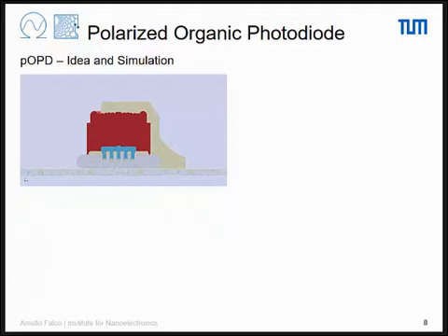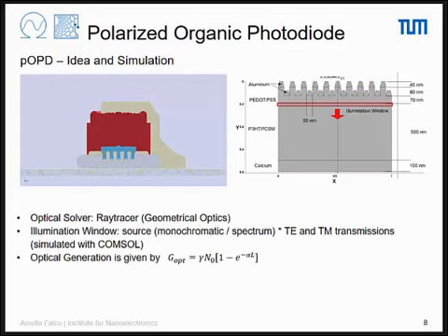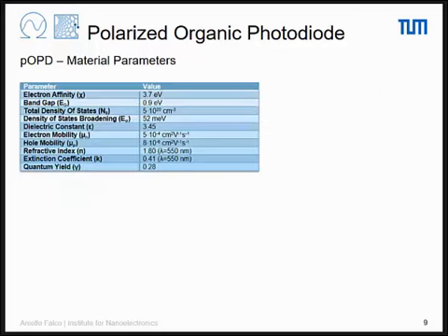We decided then to simulate it with a drift diffusion model in Sentaurus TCAD. That's what we considered. For the light, we used the most simple optical solver, but instead of giving it the normal light that we would give, like a monochromatic light, we gave the light that we simulated in the previous step. So we simulated the light that would pass through the grid lines here, would get at this level here, and then it gets inside the photodiode. Simulating this, just using a normal optical generation like standard, we obtain some good results, but first I'll give you some more details on the model we considered.